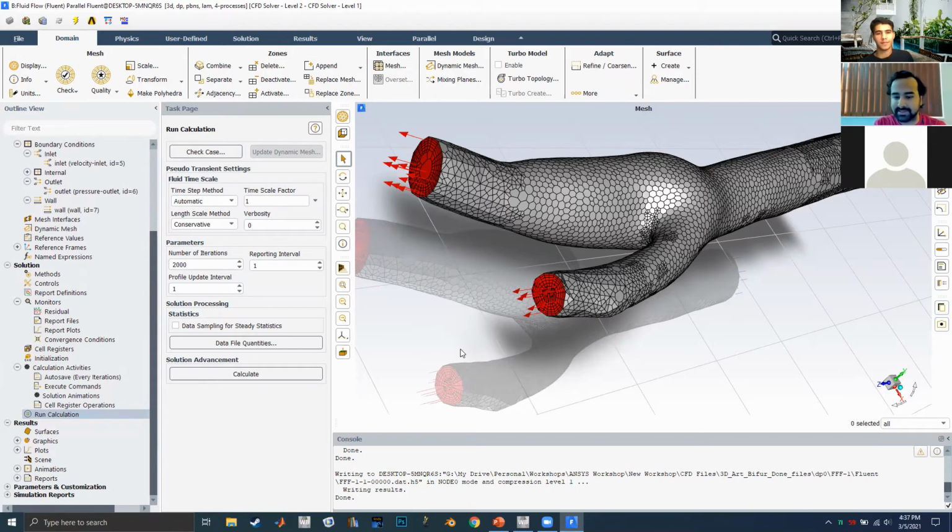Gotcha. Because the idea is for there to be a steady state solution, you wouldn't see a transient difference in your final solution if you looked at it now versus 10 minutes from now. But if your geometry has a bunch of issues that cause the fluid to flow one way, and because it's flowing this way it causes a weird whirlpool pattern that causes the fluid to go this way, and then that causes a turbulence issue over here, all that is very temporal effects, which does not lead to a steady state solution.